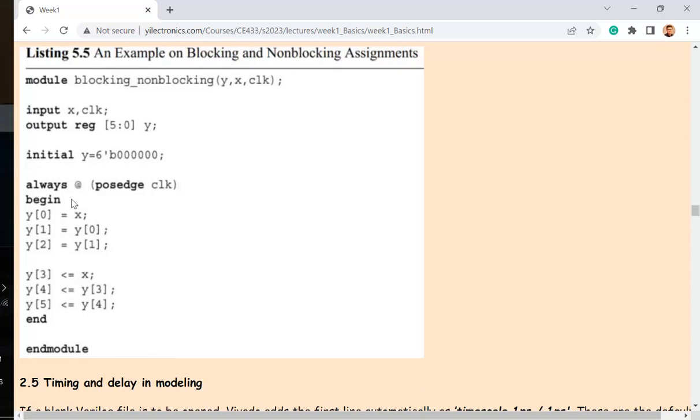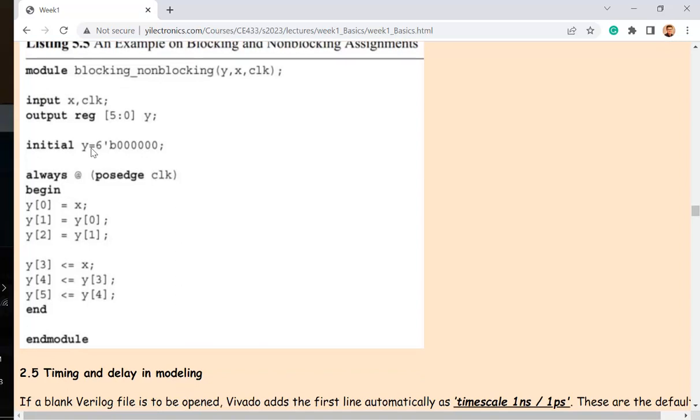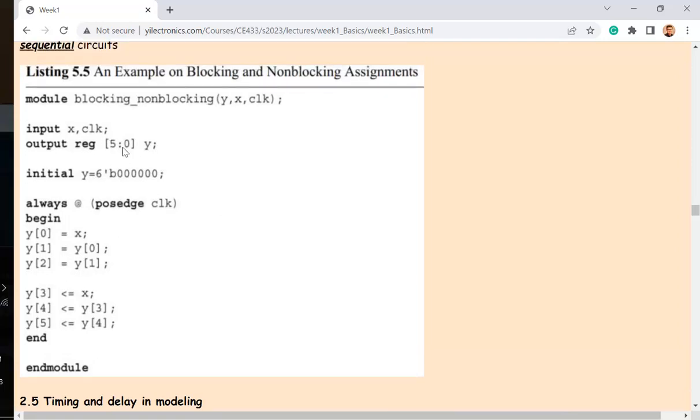Okay, so for this example, you can see that initially I gave y, which is a, and you can see this is how we form that data type. It's like an array in C++. You can see it has how many elements in there. What's the length of it? 0 to 5, right? But usually it's written as 5 to 0. It's MSB to LSB.